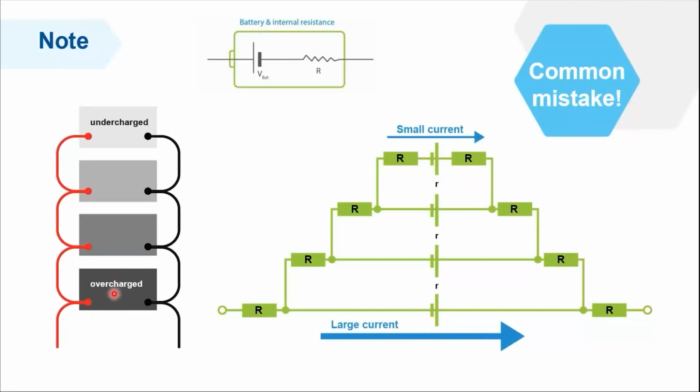So this battery will age very soon, because it will deliver a lot of power to the loads in comparison with other batteries, and it will cause a sort of unbalancing in your system, and then it will start to destroy the other batteries as well. And sometimes you will see these batteries are swelling in the field, and they change their shape because they've been used under a heavy load and under high temperatures. So this will destroy the batteries.